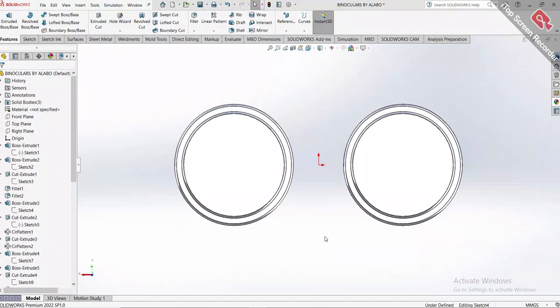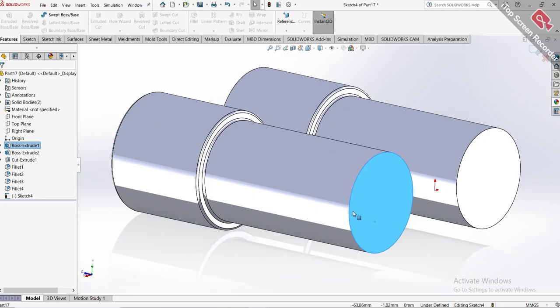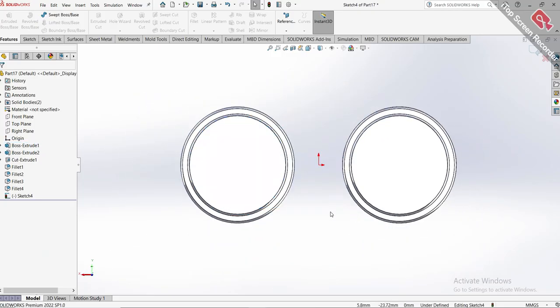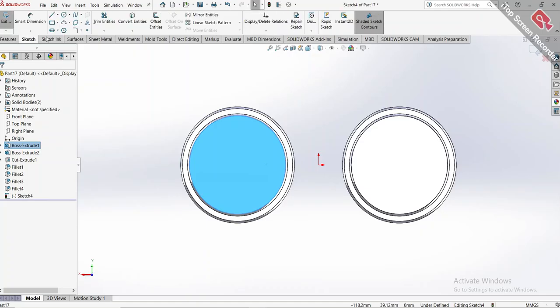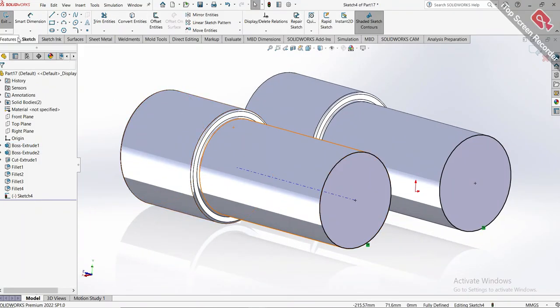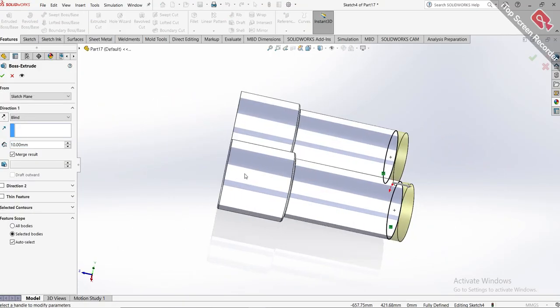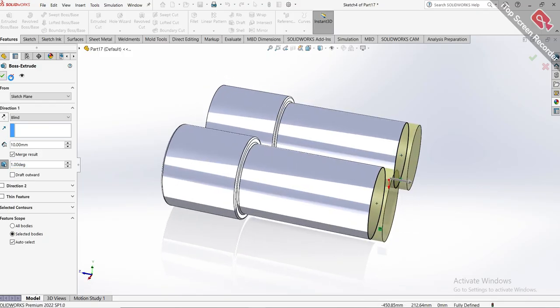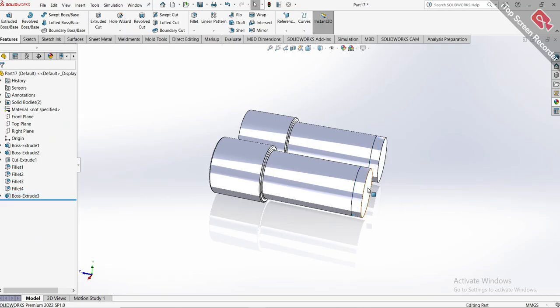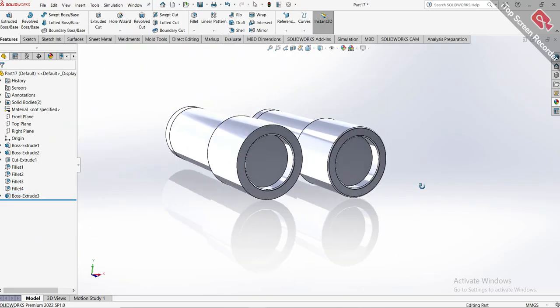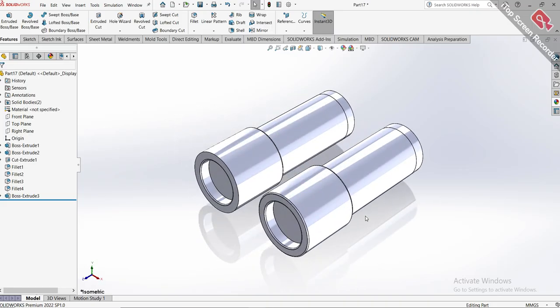So we're back to this. As you can see, we sketch there, Ctrl 8, we'll get this. Then we'll just click here. This is sketch. Click here, tap convert entities to produce back the same circle. You should be able to have something like this. Then go to features, click on extrude boss. We'll now have something like this, but we'll just make it 1 degree, just one, so that there's a little bend on it. Okay, so we can be able to produce this, as you can see now. So I've been able to get to this stage.